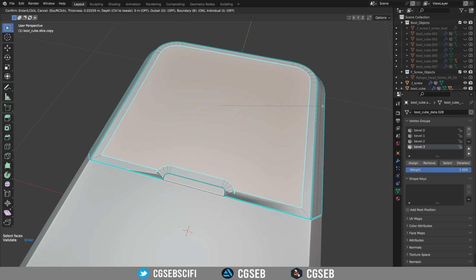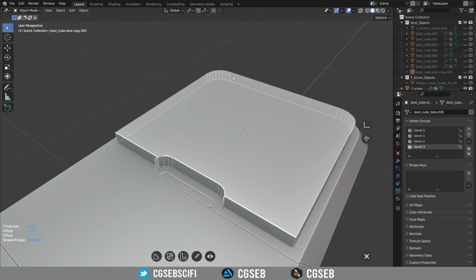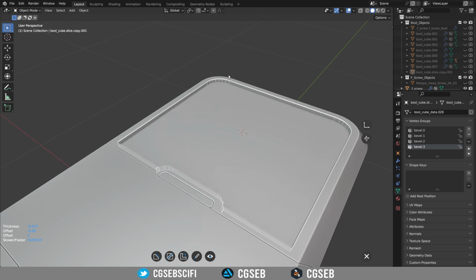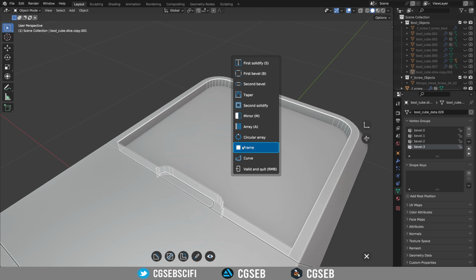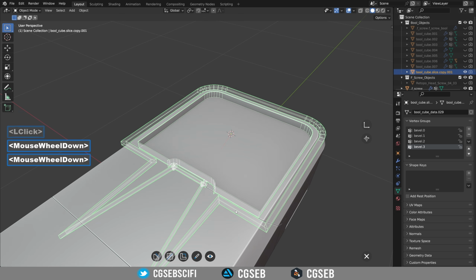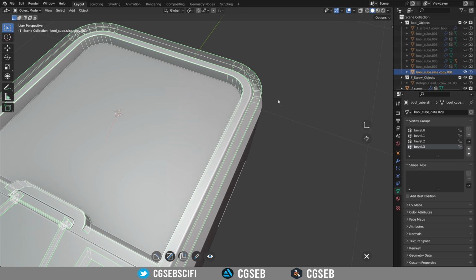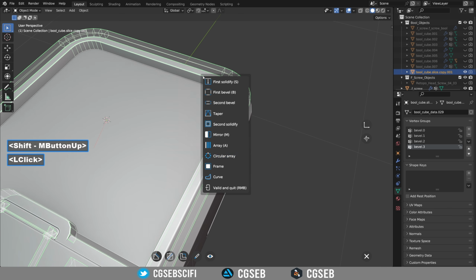So make a margin, probably something like this. Click, press enter, and this will cut the object or add the object depending of if you go inside or outside the object, like any other cutter. Go a bit inside, press validate, and use the frame tool. Adjust the depth. Don't worry about the bottom part, we will cut it afterwards, so it doesn't matter. We only need to look at the top part.